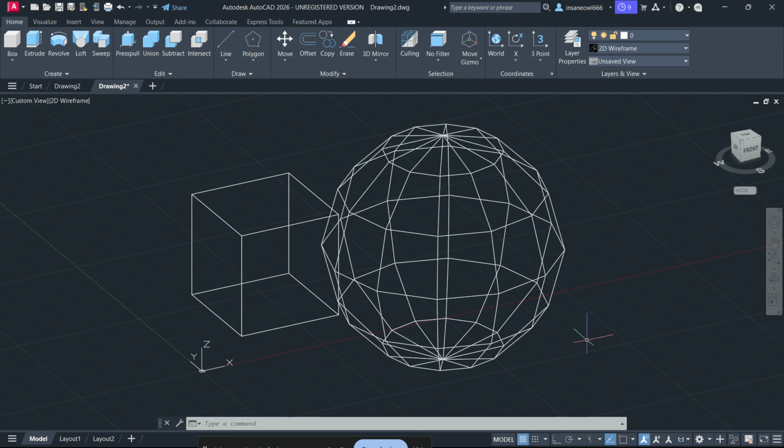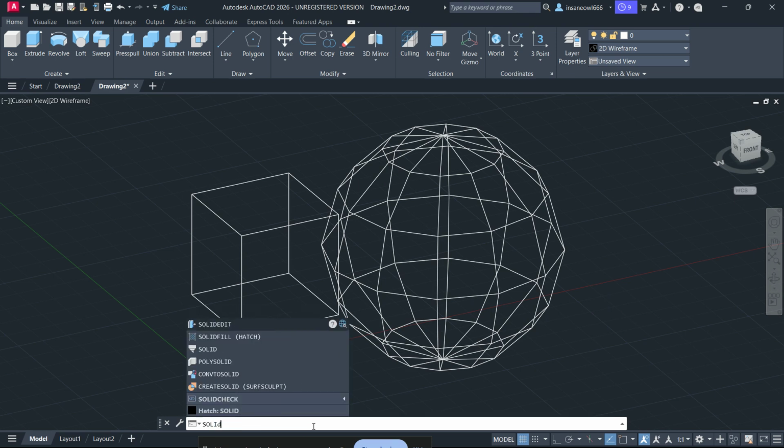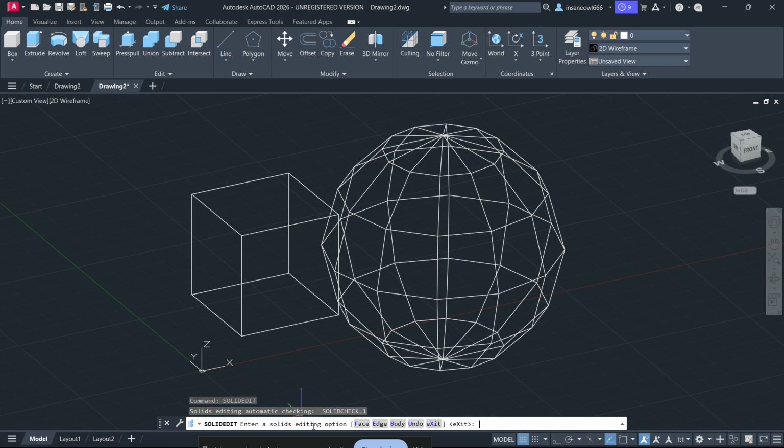To quickly recap, if you get AutoCAD error 97022, start with a micro move, then run SOLIDEDIT clean, then check the solid validity, simplify detailed features, scale the model up if needed, and use incremental union to find the problem object. Those steps will fix most Boolean failures related to this error.